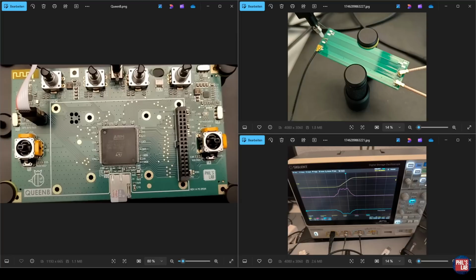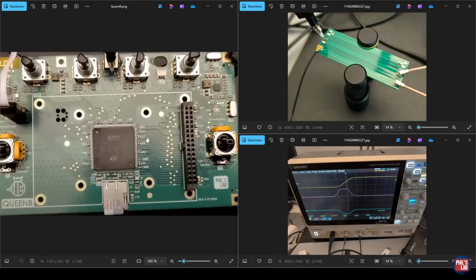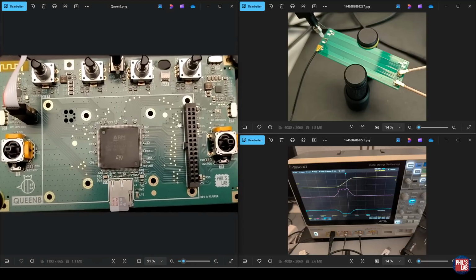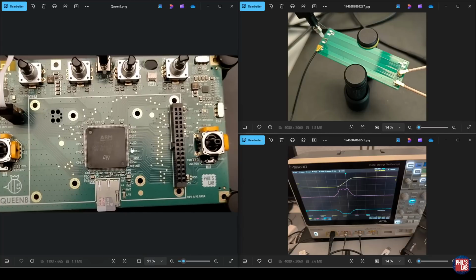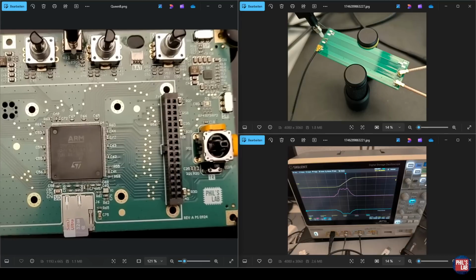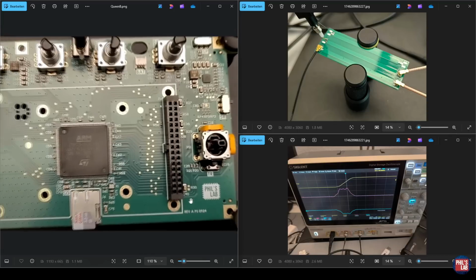The PCBs we'll be looking at for demonstration and measurements, some of which we've seen a couple times on this channel. So on the left-hand side, we have this Queen Bee radio control PCB, where I'll be doing some rather simplified crosstalk measurements of aggressor and victim traces and see how even with pretty well-spaced traces, by changing their output rise and fall times, we can get pretty aggressive crosstalk despite good spacing and despite close reference planes.